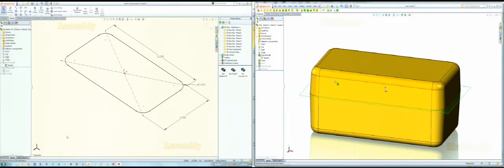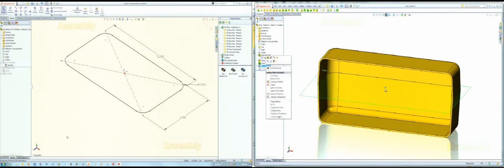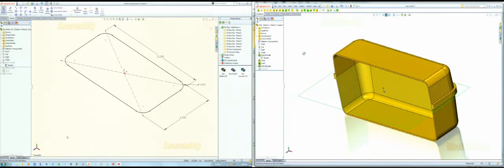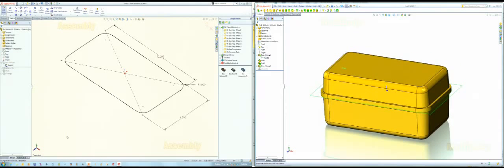Now the significant thing here is it's the same fillet feature. So we don't have to do anything fancy to connect the two values together because it's the same body. We haven't split it into two bodies yet. And then I'm going to go ahead and shell it. And I didn't pick any surfaces to remove, so what we've got is a hollow shell now. Okay? And there's a million ways to do this. This is just the way I chose to do it today. And then I'm going to add a boss all the way around the outside. Still got one body, but I've added that boss because that's going to be where our lip and groove is eventually going to go. And then I'm going to finally split it apart. And the way I'm going to split it apart is using a new 2013 command called intersect.